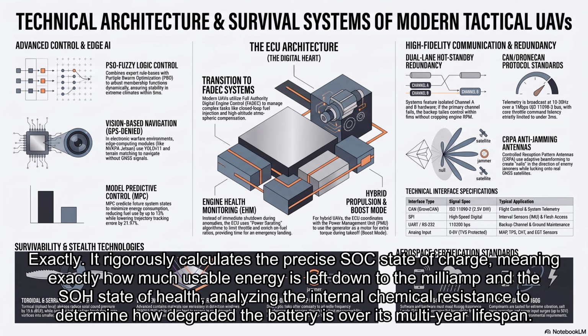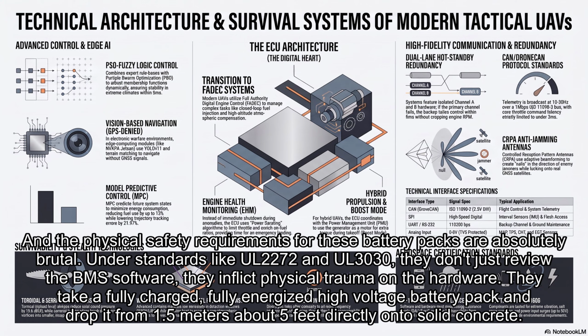Exactly. It rigorously calculates the precise SOC, state of charge, meaning exactly how much usable energy is left down to the milliamp, and the SOH, state of health, analyzing the internal chemical resistance to determine how degraded the battery is over its multi-year lifespan. And the physical safety requirements for these battery packs are absolutely brutal.